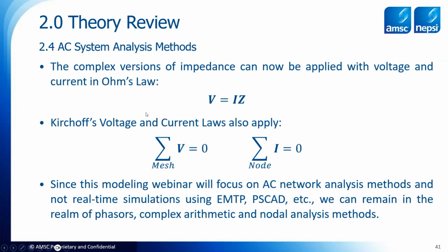So V is equal to I, not times R anymore, but times the complex number Z, or the impedance. And all of these are vectors. Similarly, Kirchhoff's voltage and current laws also apply with phasors. So the sum of the voltage phasors around a mesh or the current phasors injected into a node are 0.